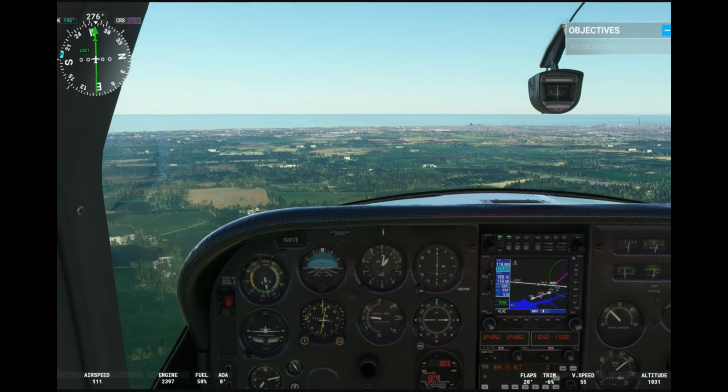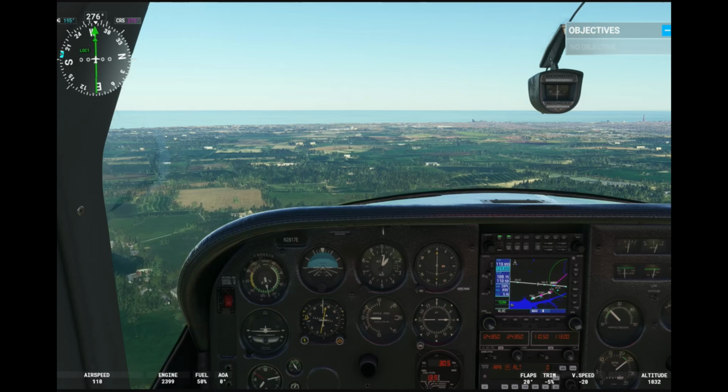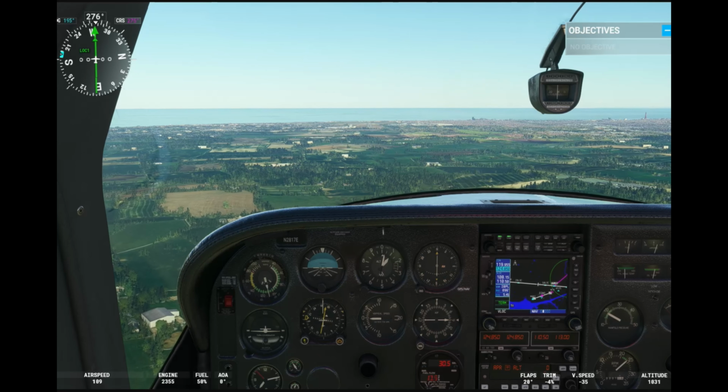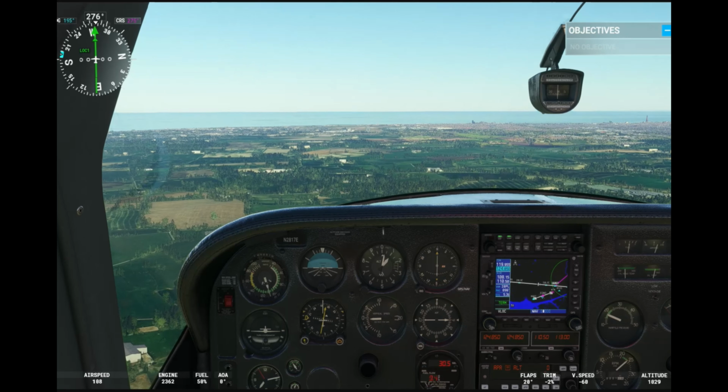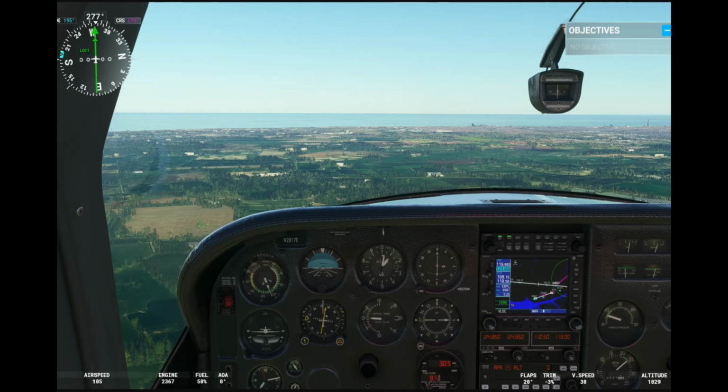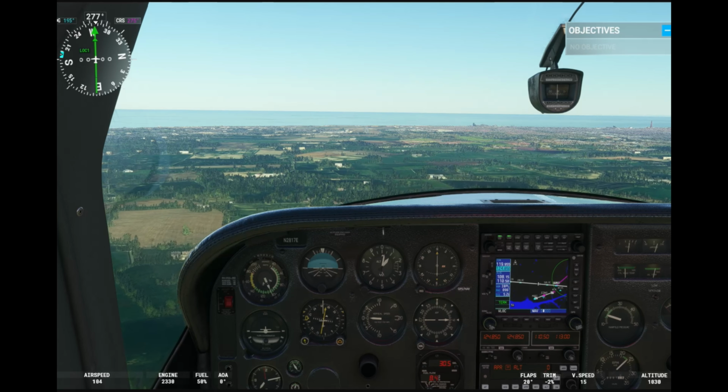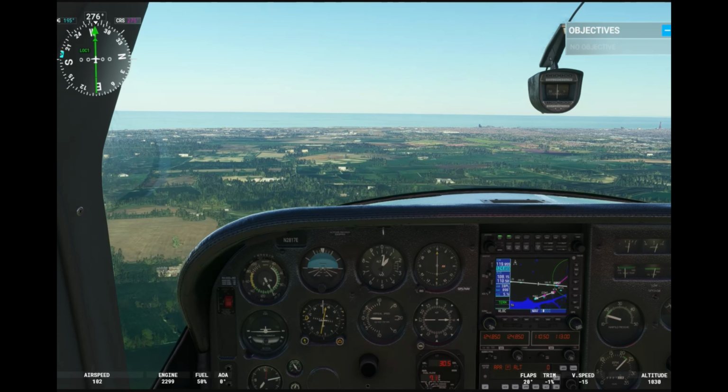And you'll see also when the horizontal line on the direction indicator starts moving downwards, we're then on the glide slope, which is normally about a 3-degree angle, something like about 350 to 500 feet a minute.